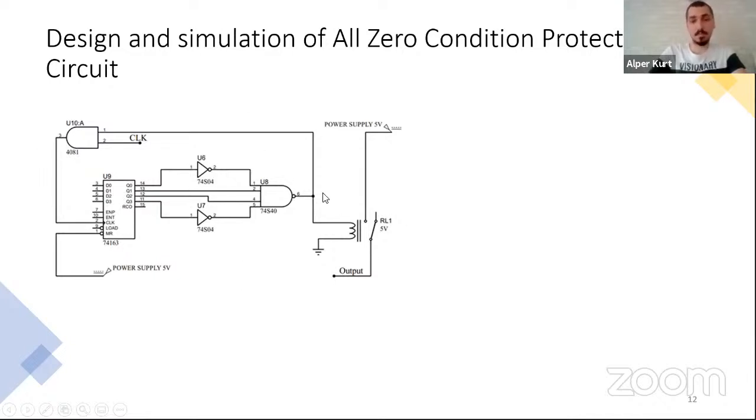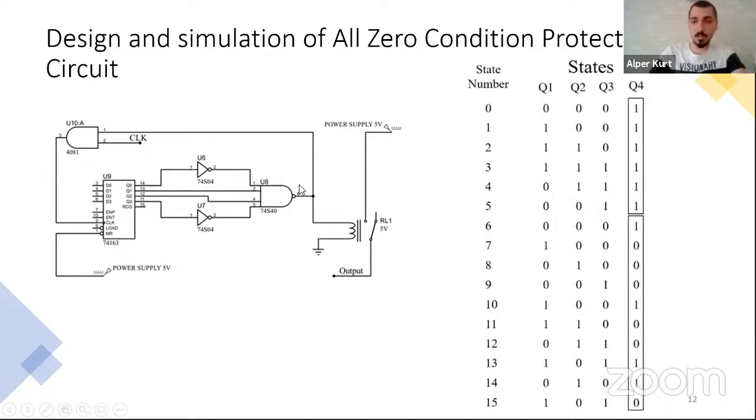So this is the basic idea of the circuit, and you can see all the states of the LFSR with protection circuit. You can see that for the first 6 clocks, it ensures that this node becomes a 1. It is forced to become a 1, and after the 6 clocks, the PN sequence generator will operate as it should.